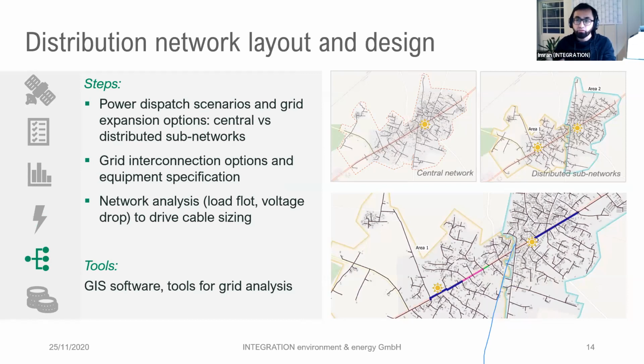That means that we also have to plan for circuit breakers and further safety devices at transformer locations, and also if there is a need to install bulk meters to allow for recording of the units that are being transferred from the grid or the other way around.